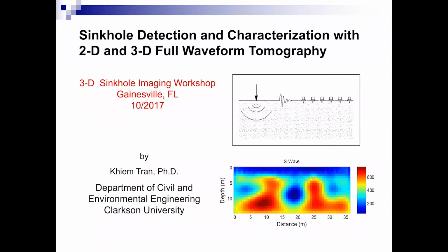So here we have a shear wave velocity profile. We have a blue zone on the top here, soil. The red area here is limestone. The blue zone inside the limestone here is a void. So the goal is to measure the data on the surface and then identify the embedded void, go to 50, 60 feet depth like we usually do with our equipment.